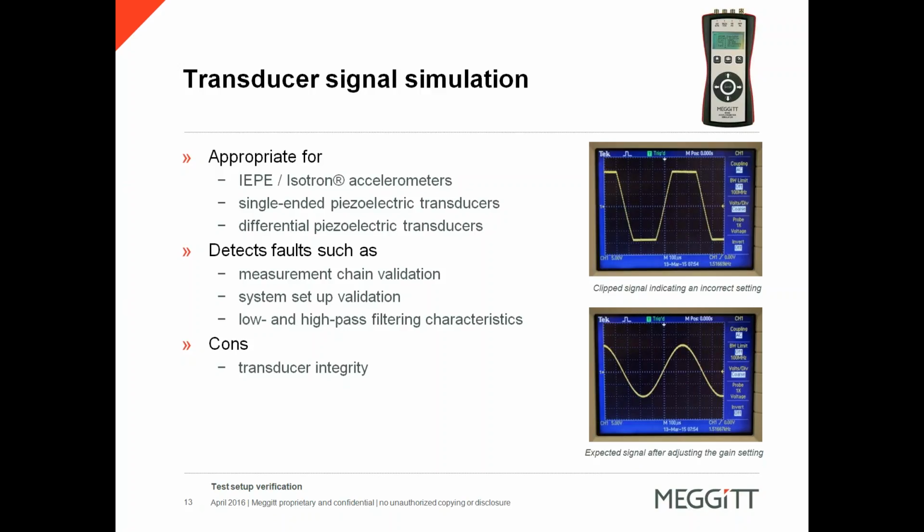The output can be set in picocoulombs for complete channel setup. The signal is adjustable in both frequency and amplitude, making it a very dynamic test that can identify channel noise as well as verifying out-of-band frequencies to ensure appropriate filtering is enabled. Yep, all of these simulation methods are great for system setup verification.